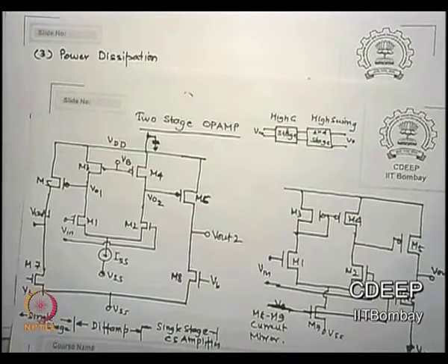Have you seen it any time, or have you never connected one? All power supplies should be connected through bypass capacitors to minimize the variation in VDD and VSS, which will improve your PSRR values, okay, is that clear? So we do not really do great things in PSRR externally. Internally we can do a lot of things, but for external people you still have a choice to put a capacitor. But what is the problem with a capacitor? It will remove only some frequencies, is that correct? Because it is a low pass filter, so it will cut only some of them, okay.